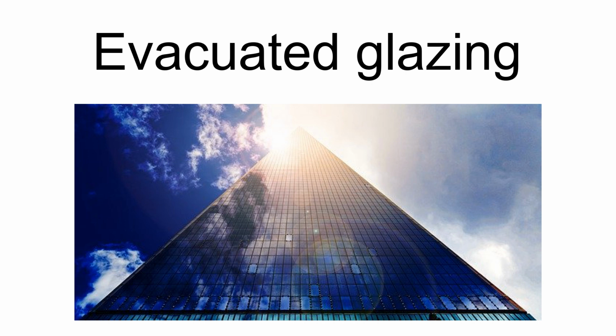Furthermore, because of the atmospheric pressure present on the outside of an evacuated glazing unit, its two glass sheets must somehow be held apart in order to prevent them flexing together and touching each other, which would defeat the object of evacuating the unit. The task of holding the panes apart is performed by a grid of spacers, which typically consist of small stainless steel discs that are placed around 20 mm apart. The spacers are small enough that they are visible only at very close distances, typically up to 1 m.